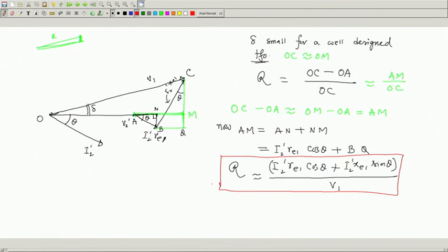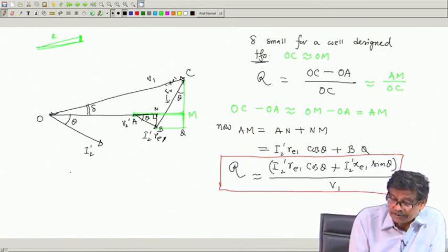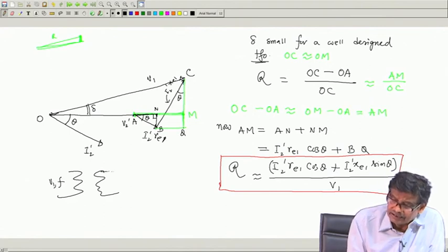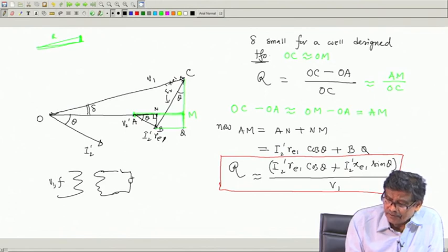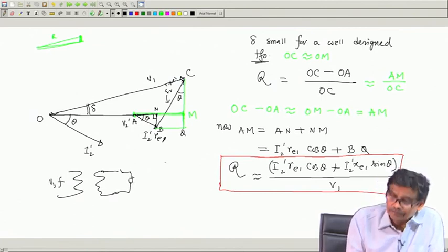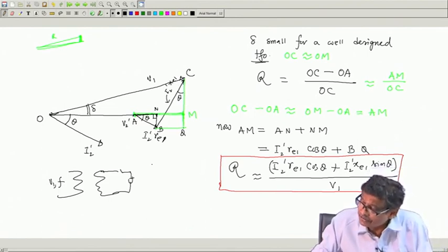Now, what is the use of this expression? Regulation is so simple, otherwise even without doing mathematics, as I was telling, just energize it with rated voltage and frequency in the lab and then connect the load. Measure with this switch open what is the voltmeter reading, close this switch with this load present, take the difference of these two voltmeter readings divided by the open circuit voltage, and it will give you regulation. Then why have I found an expression?